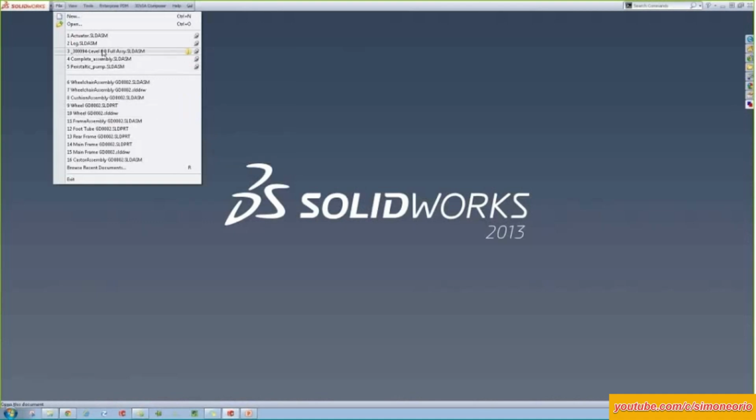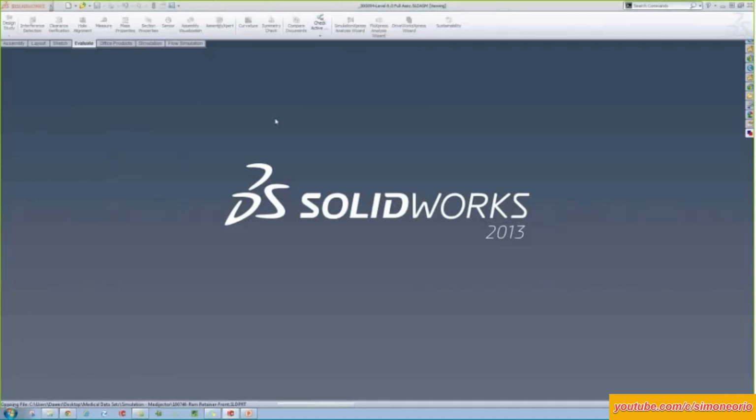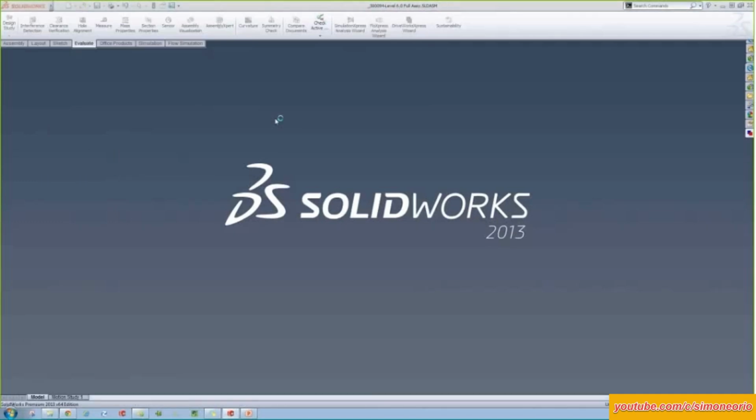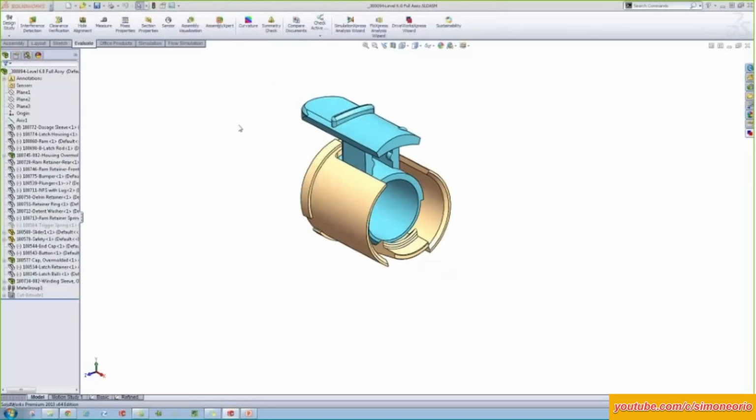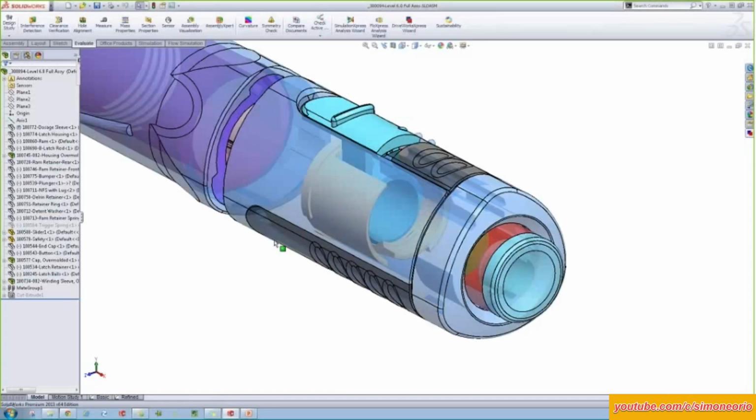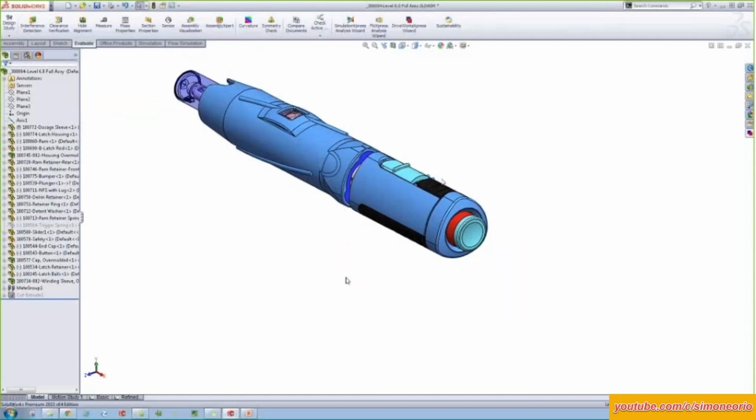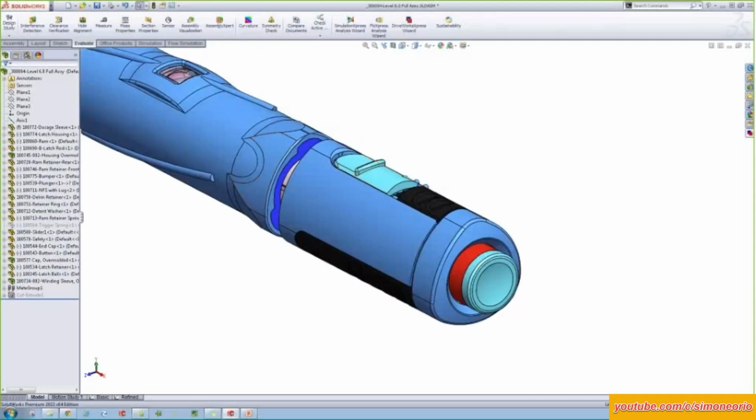And we'll grab this is the meta ejector with just a bunch of the components hidden. They're still in there for the simulation. They're just hidden so we can easily view the key aspect of it. And that's just as easy as setting up a display state. So we've got display state 1 with everything in there, including this teal snap. And I've set up a display state that only shows the lock.